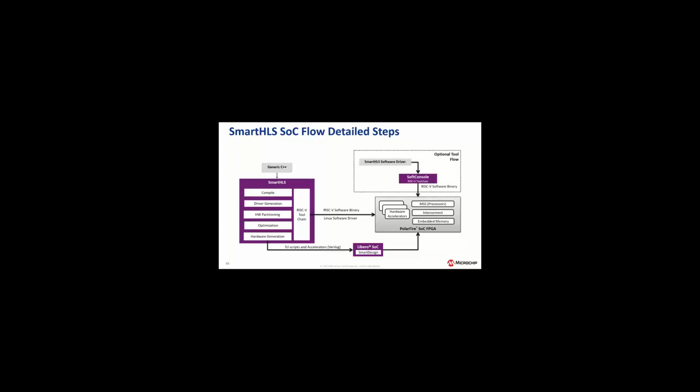Right, cool. All right, so if we take from a perspective of, as I said, we're going to have some level of core in there, be it soft core, hard core, however we decide to put it in there. I'm going to have my C++. A couple of things it's going to generate for me: I'm going to need a driver. But I've got to tell the software, if I'm running it in the core, how to talk to the hardware I've just created. So it will generate that for you, thankfully.